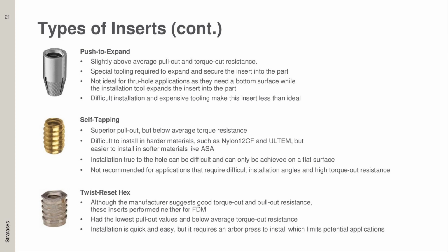It can be hard to install self-tapping because you're doing it by hand, so you risk inaccuracies and making sure your insert is nice and aligned with the axis in the hole. And so it's not recommended for applications that require unique angles or a challenging angle or something that has a high torque out resistance.